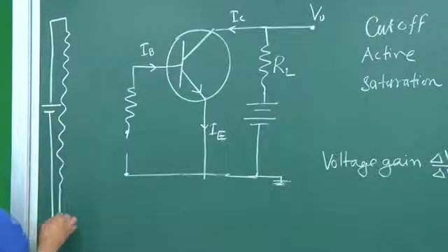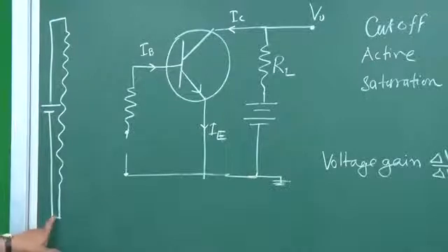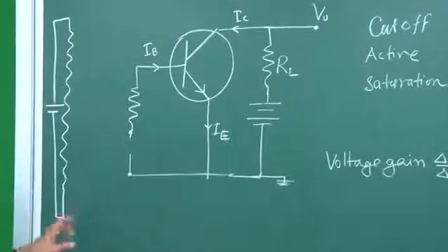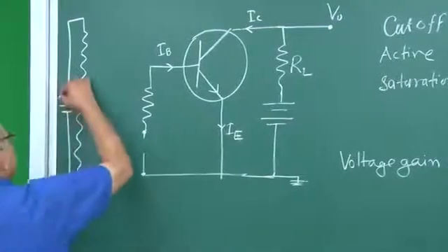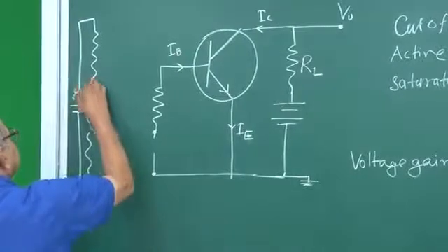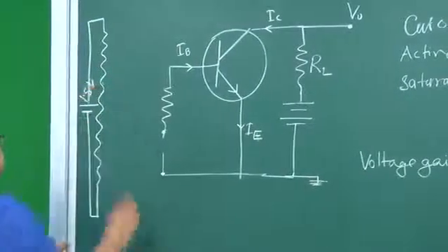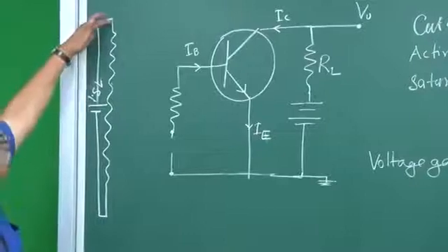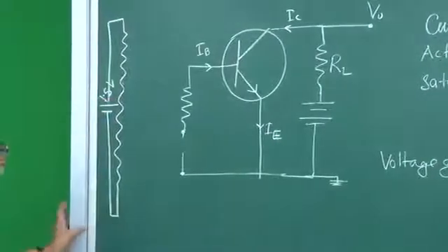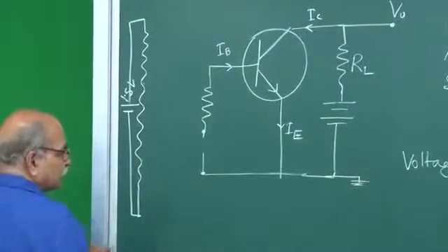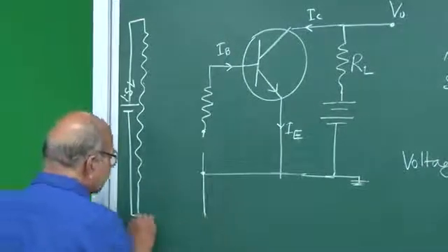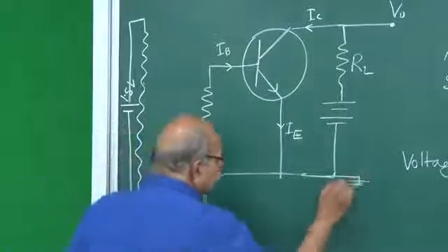like this. We will be putting a switch here, or we will be connecting it at the time of actual measurements, but in the diagram I am showing it connected. So this is a 1.5 volt cell, right. So the total drop from here to here is 1.5, and this negative we will take as the 0 potential. So this is actually connected to this ground.